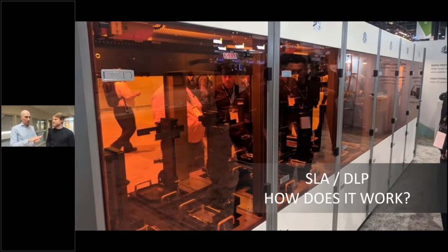So in this technology, you have a resin or a liquid that's UV sensitive, and then you cure this with a laser. So a UV laser hardens the material, and then you raise or lower the part out of the liquid. Right. So layer by layer. Layer by layer. Yeah, exactly. Right. So this is actually the first 3D printing technology that was invented in the 80s. So it's been around for a long time, and it has a really wide array of materials.